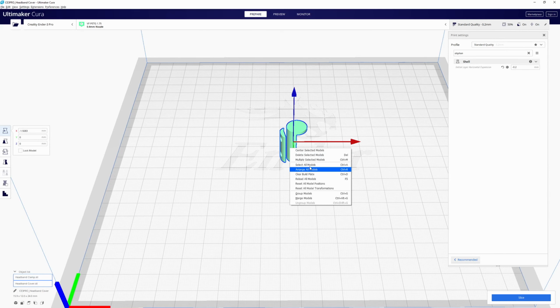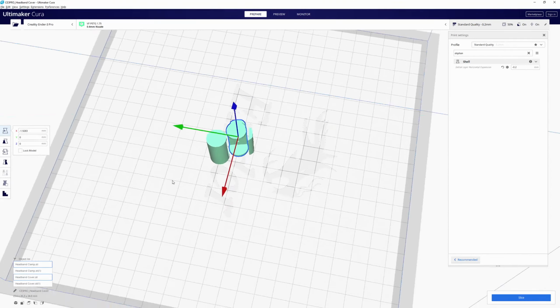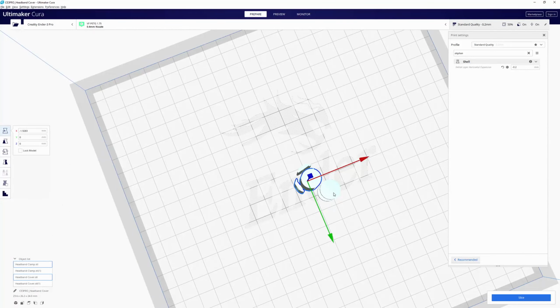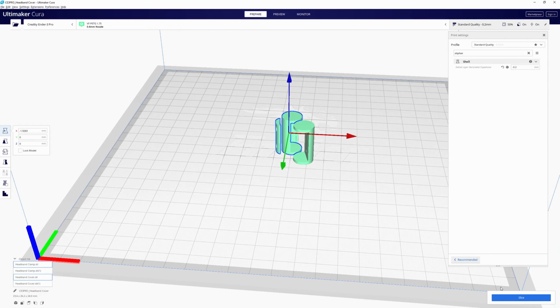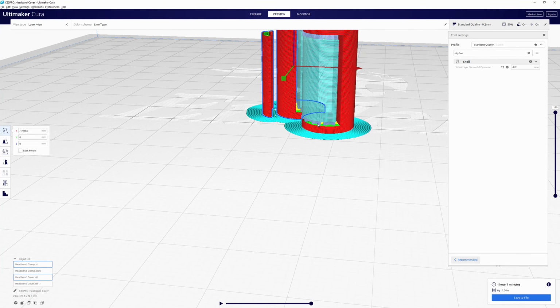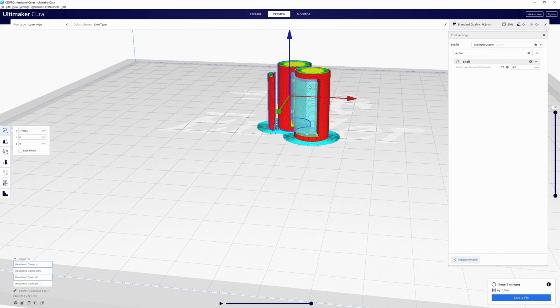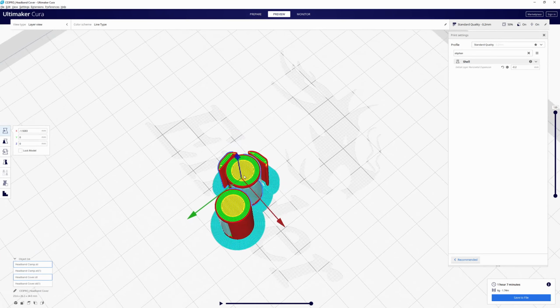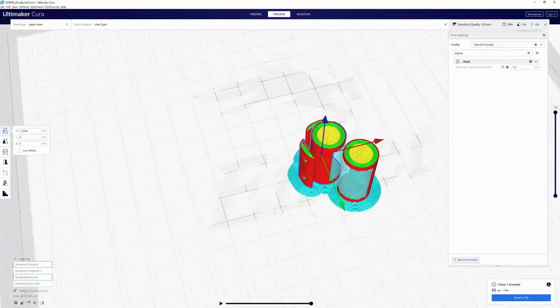The one thing is that you will need 2 of them, and we often will print these all together. The arrangements are always a little bit weird in Cura, but the standard support settings work great for the covers. You can see that they put that support interface on both sides. Just be a little bit careful removing them. They can snap off in an odd case, but luckily this is such a small part that it's no problem to reprint if you have troubles with that.